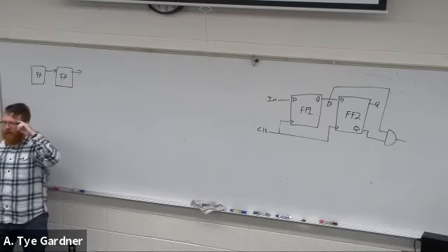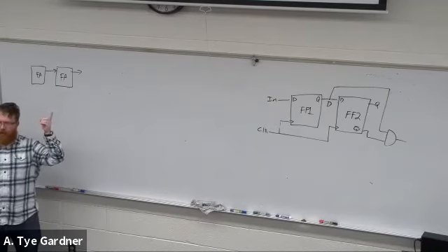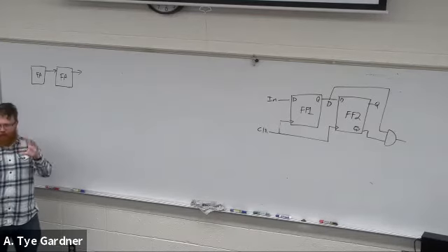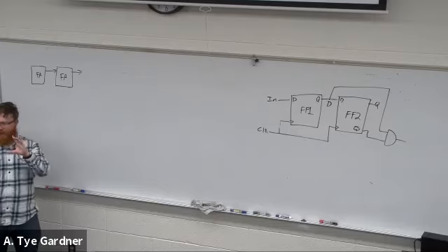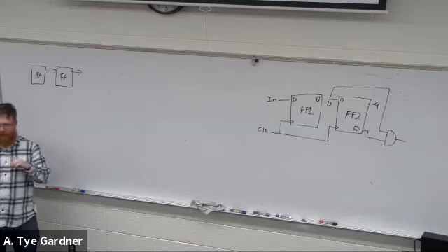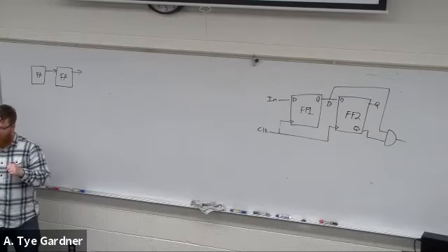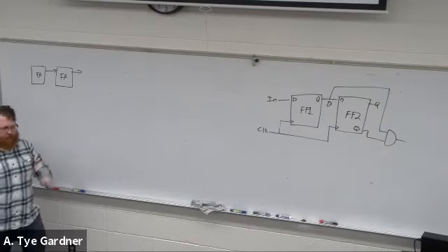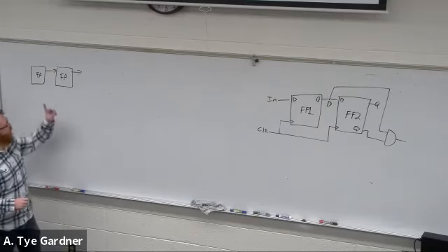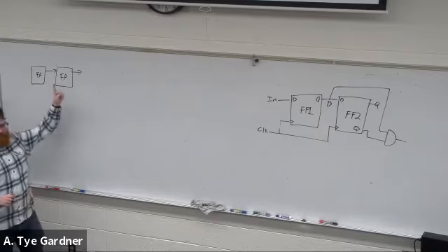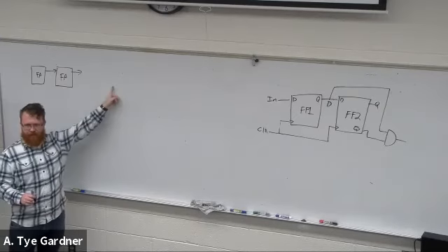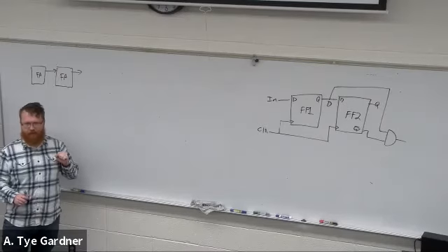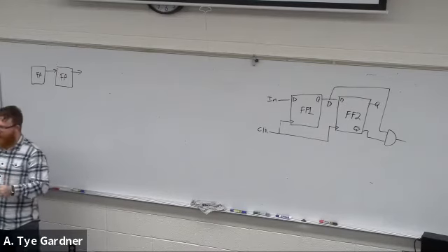right? Because if you just use the direct solution method of K-map, you will always end up with 2 tiers, right? The ands and ors and ands, sum of products, product of sums. 2 gate delays is your minimum. Realistically, most of them end up with 3 gate delays because it takes fewer gates to do it that way, right? Which I won't get into yet. So every bit I add adds an additional delay. If I want to add 32 bits, like a lot of operating systems kind of do, that takes a very long time.